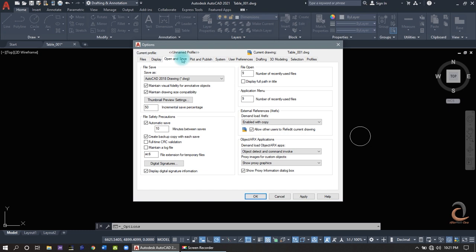If you are using the 2021 version of AutoCAD to do a project which a colleague using the 2007 version of AutoCAD is going to work on, saving this project in this 2018 default format will make it difficult for the one using 2007 AutoCAD to work on the project. You get a scenario whereby the file you sent to the colleague can't open on his own AutoCAD. So you can choose the format you know will be best for you both and set it as the default format.